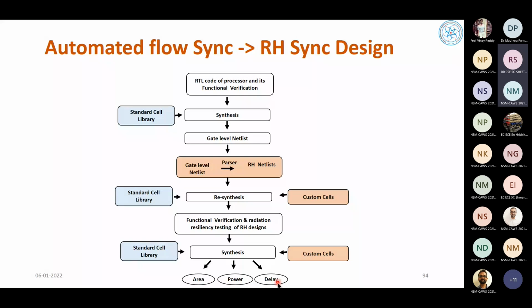This standard cell library has the power values for every gate. When a NAND gate switches from 0 to 1, how much power will be consumed? That is written in the standard cell library, which is provided by the foundry. So if I'm using, let's say, 5 NAND gates, and 3 of them are switching, then I can manually calculate what power it is going to take.